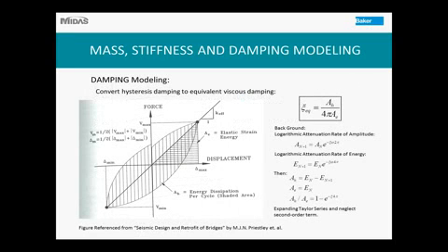Now, for the modeling of damping, damping is a very complex problem, so it's really hard to capture in the model. Our structural damping usually comes from hysteresis damping, like in this loop shown here. It's a nonlinear response of your lateral resisting system, and every loop is going to take away some energy from the system. The energy taken away per cycle is what we call Ah, the energy dissipation per cycle. And then the strain energy of your system at the beginning of the cycle is called Ae. And this is a hysteresis damping system.